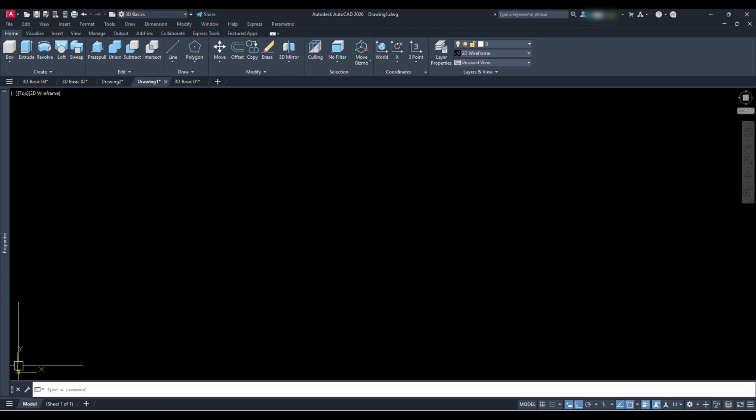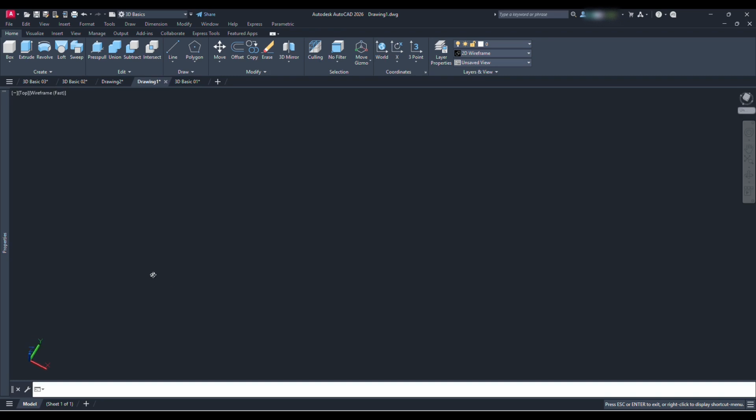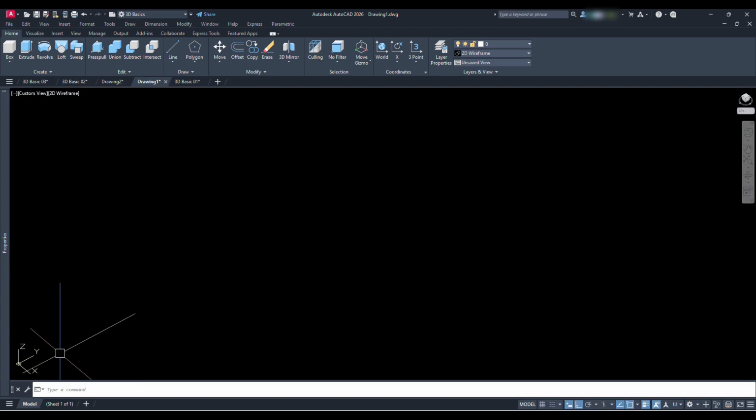Here, we are viewing on the XY plane. Whatever 2D figures we create in this condition will all remain on the XY plane at 0 height until we provide or mention the Z elevation. We can call this view the top view. We can keep pressing the Shift key, then click and hold the mouse roller and move the mouse until we like the view angle. Like this. Now we can see 3 planes: XY, YZ and XZ.